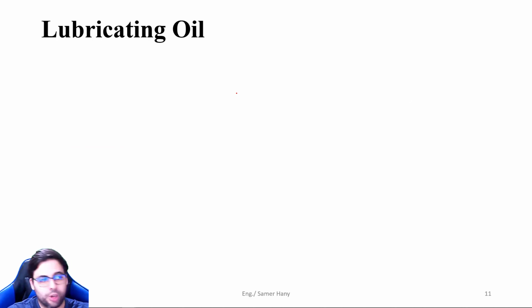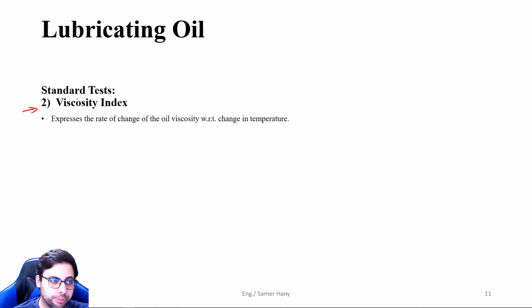Okay, so measuring the viscosity by itself is not enough. We need to know if that viscosity will be maintained even when we increase the temperature, right? So we don't want this viscosity to drop dramatically when we increase the temperature. So here comes the second test, the viscosity index, which expresses the rate of change of the oil viscosity with respect to temperature change.